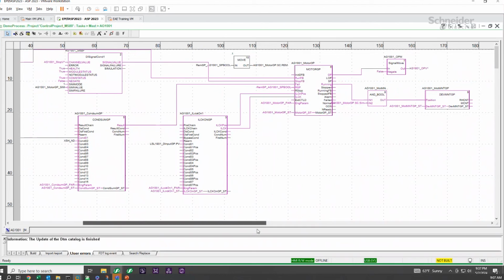If we don't have maintenance defined for this, if we don't want to record runtimes and numbers of times started, then these blocks here are not created. And so we tailor the logic to the specific application that you've defined for each instance. This is instance by instance. And so that saves on memory, it saves on data footprint, and really helps to optimize the system.